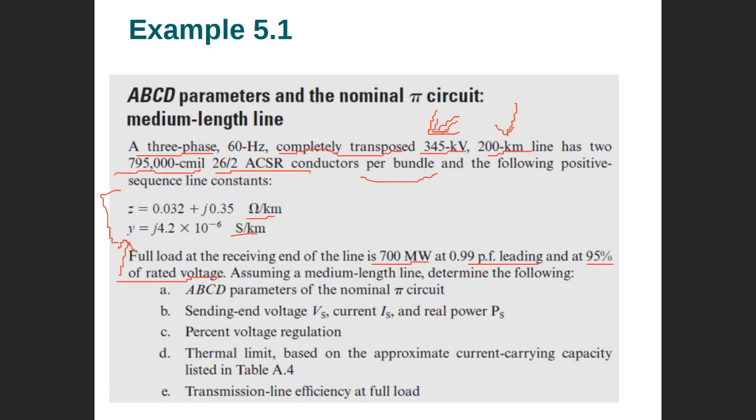And what is the load? This is the load power, real power, and this is the reactive power. This is the power factor, leading. Therefore, you can determine the reactive power, and the reactive power will be negative. Why will it be negative? Because this is the load, and the load is now injecting reactive power into the system. How do we know? Because it's a leading power factor.